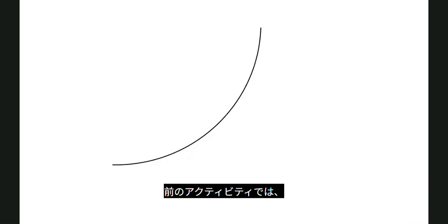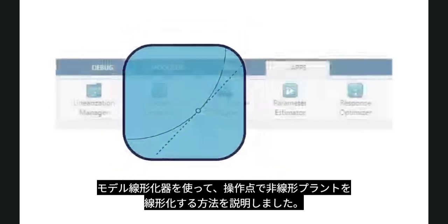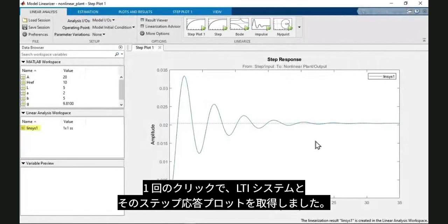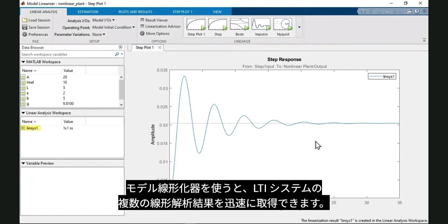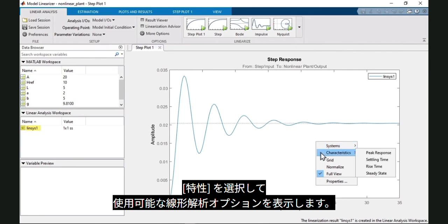In the previous activity, you saw how you can linearize a nonlinear plant at an operating point using the Model Linearizer. With a single click, you obtained an LTI system and its step response plot. With Model Linearizer, you can quickly get multiple linear analysis results of the LTI system. In the step response plot, right-click on a blank area, then select Characteristics to show the available linear analysis options.